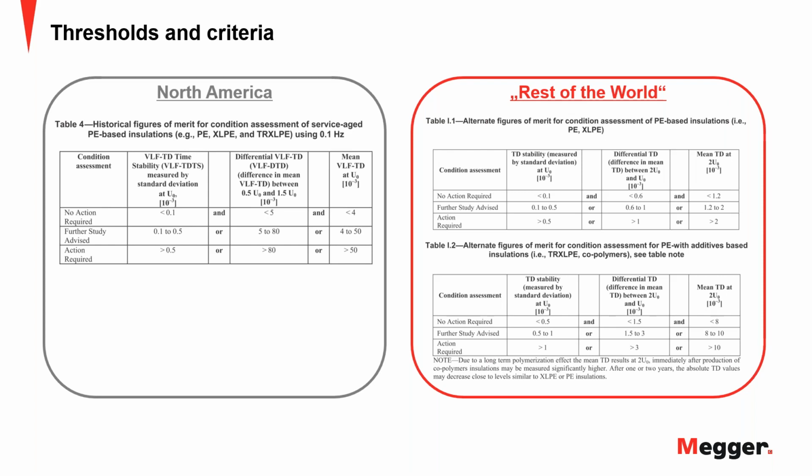The reason is, we explained the stuff with the copolymer cable, the additives, the cable has not yet seen load, the falling tan delta over the lifetime of the copolymer cable, the influence of the accessories and whatnot. Then even external conditions, humidity, maybe dirt on the end terminations, so you have additional creepage, so then it becomes a guarding problem maybe, or a cleaning problem, all of these things.